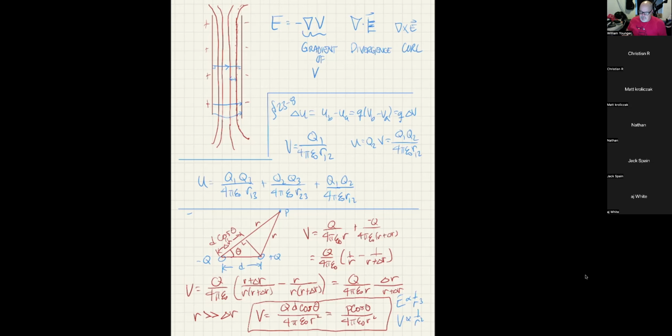Turns out they're sort of the opposite of resistors. For resistors in series, the net resistance becomes the sum of the two, but for resistors in parallel, the reciprocal of the net resistance is the sum of 1 over the resistances. Well, it turns out capacitances are just the opposite. So capacitances in series add like reciprocals. In other words, 1 over C total is 1 over C1 plus 1 over C2 plus and so on. And weirdly enough, capacitances in parallel add. So you get C total equals C1 plus C2 plus C3.